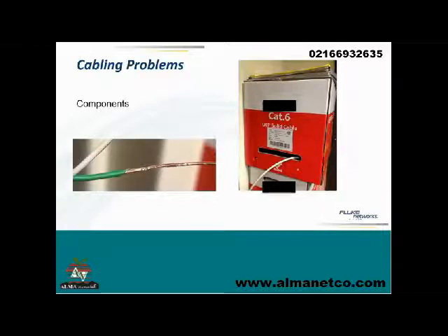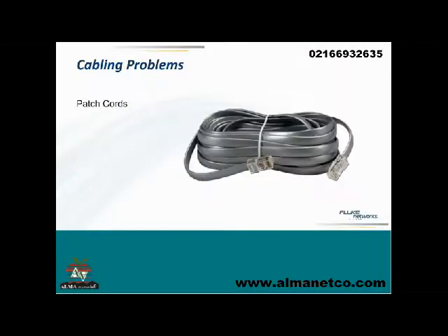Also, some of the resistance measurements can help you find that. The biggest problem with this is that it has real problems with power over Ethernet, but in general, the quality is not that good in the first place, and you can have all kinds of problems with this. If you buy from a respected manufacturer, you have almost no chance of running into this problem. But if you've got a contractor or somebody who's really cutting corners, be careful, watch out for this. We have a white paper on this topic, by the way.